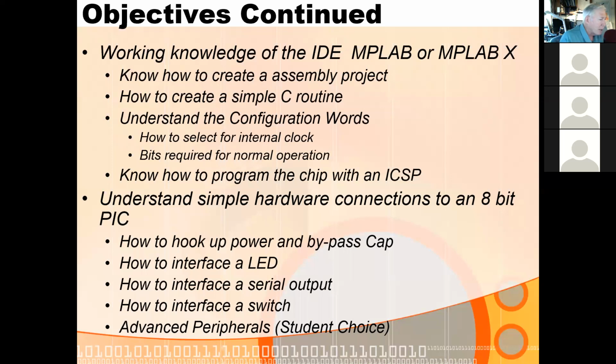And then we're going to have you interface a bunch of peripherals. We already talked about that. We've got the little analog board that plugs in, where you're going to have a temperature sensor, a potentiometer, and a photoresistor. And then we're going to have you hook up the 2-line-by-16 LCD display and control it with I2C using a little buddy board on the back with a PCF 85-something or other, I forget. It's got a chip that does that for us.